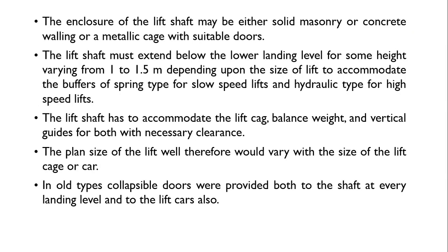The enclosure of the lift shaft may be either solid masonry or concrete walling or a metallic cage with suitable doors. The lift shaft must extend below the lower landing level for some height, varying from 1 to 1.5 meter depending upon the size of the lift, to accommodate the buffers, of spring type for slow speed lifts and hydraulic type for high speed lifts.